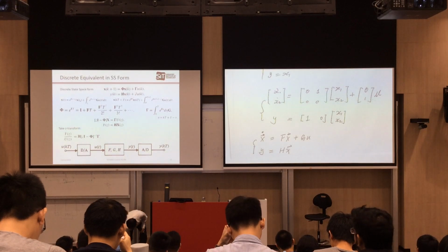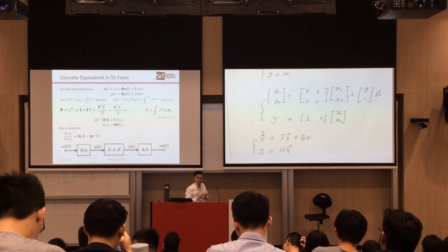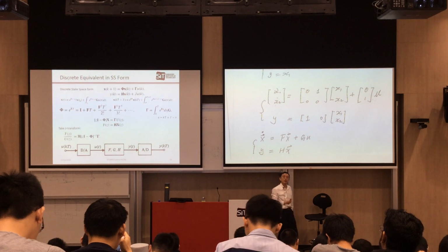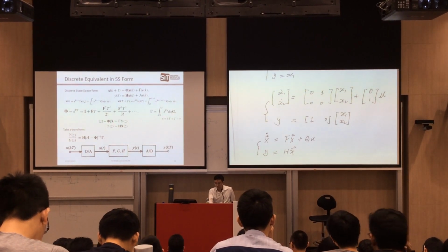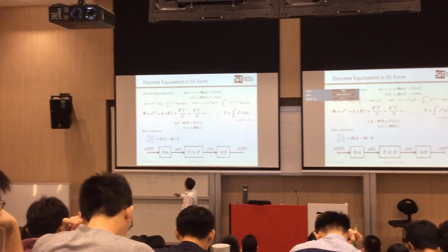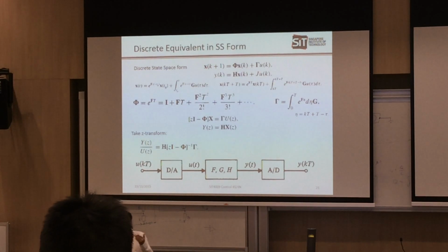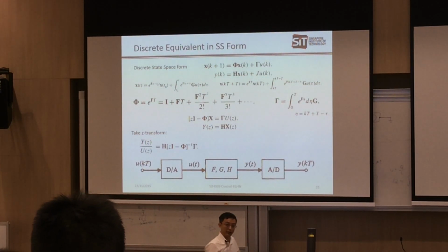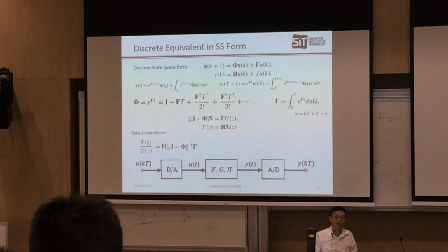Now, in my class, we are going to focus on how to get the equivalent digital discrete functions. In the state space function, if we are going to see a digital one, basically it represents your differentiation in the time domain by a difference function. So we want to see what the difference is between your continuous state space and your digital state space.